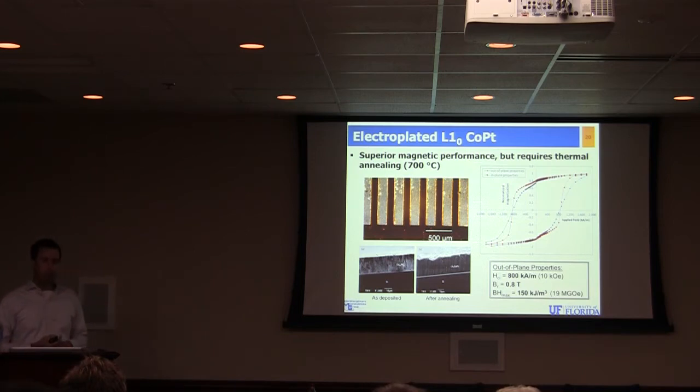No field. So if you heat them above Curie temperature, there's no magnetic property. There is no remnant magnetization. Correct. So what would applying a field do? It causes it to have uniform remnant magnetization on annealing? Uniform magnetization. You don't want the domain structure. You want the whole specimen magnetized uniformly.